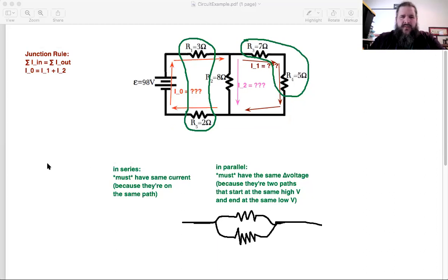Given the resistances, how do we find voltage at resistors? To figure out the voltages, it actually helps to find the current first, or some of the currents. Because we can figure out the voltage on the battery. We know the battery adds 98 volts. So let me draw this in again. Let's say this region is a low voltage region because it's right before the battery, and let's call that region 0 volts.